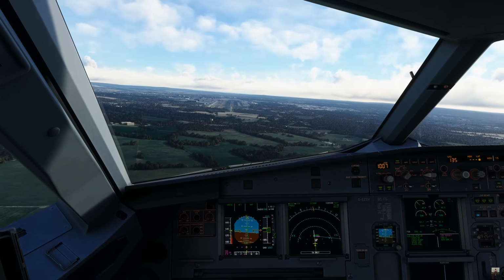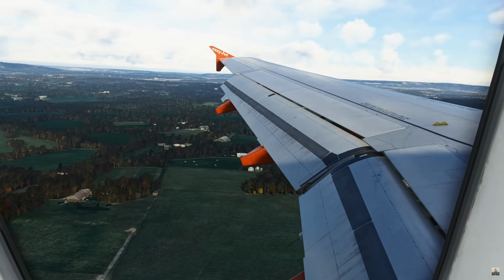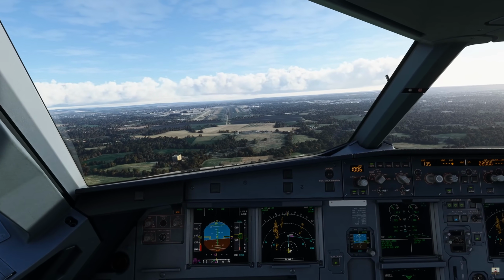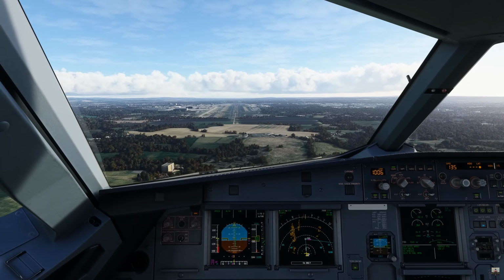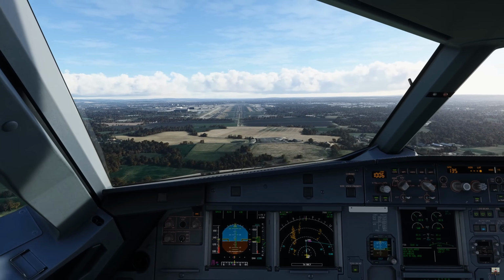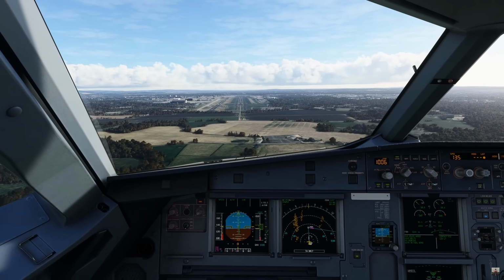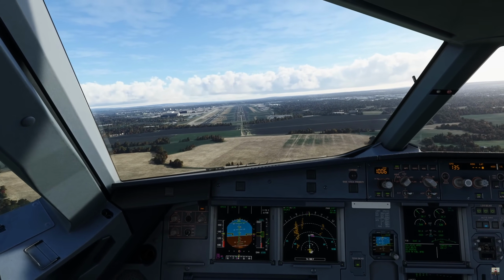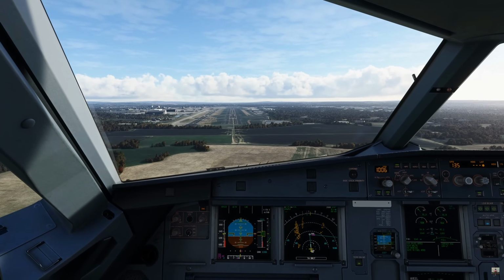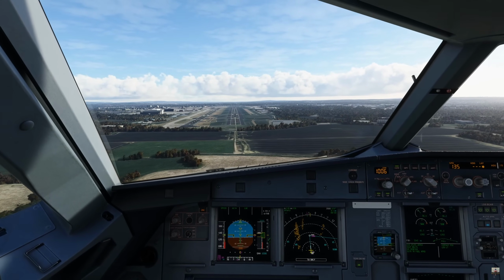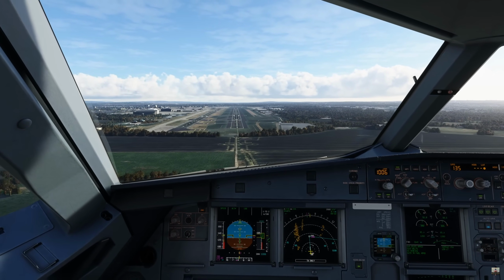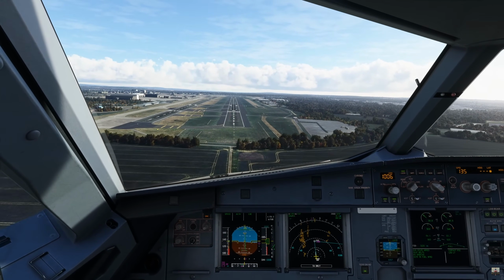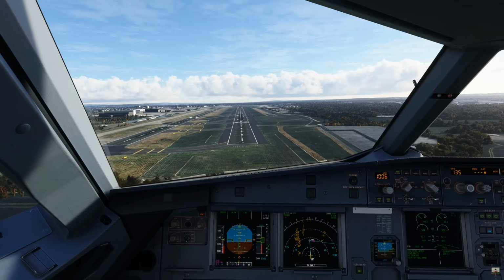So let's take a moment to reflect on everything we've covered today. So in chapter 1 we've covered understanding the MCDU. We've explored the layouts, the buttons, the functions. We've then programmed our flight plan, including departure waypoints and arrival routes. We've set up our V-speeds, flap settings and thrust levels for departure. We've then showed management of the MCDU in flight and showed how the MCDU manages navigation with redirecting to waypoints and then setting up our approach and landing phase through inputting various bits of data such as your temperatures, your winds and your barometric pressures.